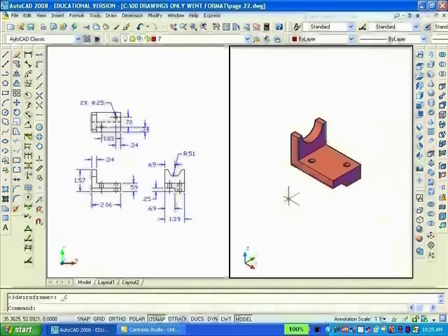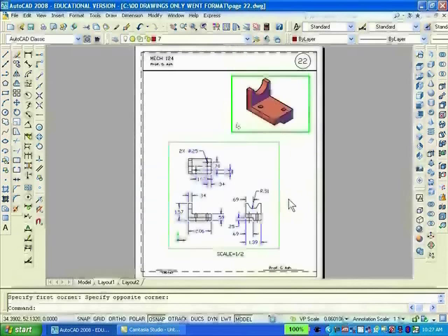When that is done, I'll shade the object and the solid is complete. Then I'll set up the two viewports as desired in Paperspace, freeze the viewports layer, and this drawing will be completed.